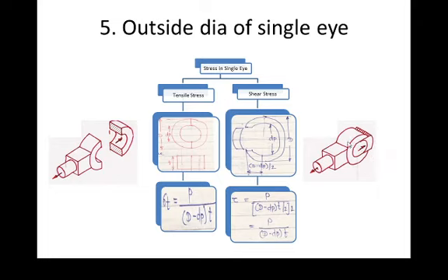It is the thickness into capital D minus dp, taking only the radial portion on this side, divided by 2, then multiplied by 2 because there is double shear.